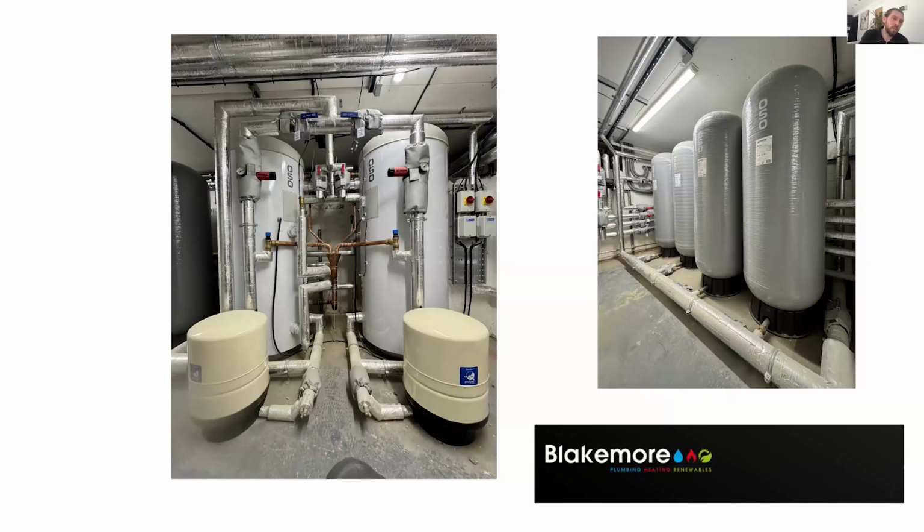The challenge here, which I didn't find out until this job, is that you can't use one combi block. You've got to use two combi blocks, because G3 states that if they're not piped in series, if they're piped in parallel, then they're classed as separate cylinders. You can't class them as one unit. That's why the pipe runs up the left and comes across quite unsightly, because I was just going to pipe it in one and come out with the other. So we've had to use separate discharges, separate combi valves, separate expansion vessels to satisfy that. You can go on again.